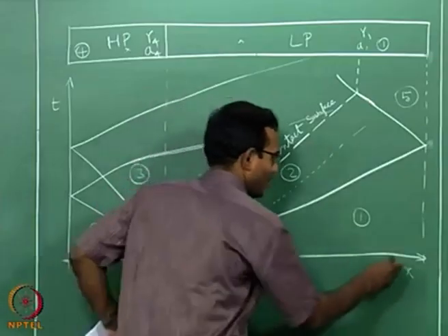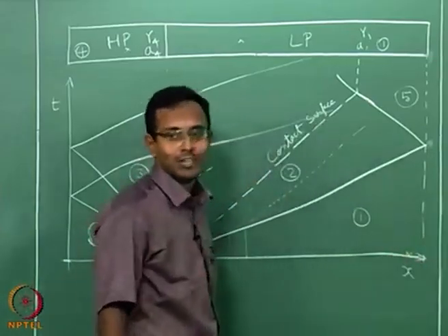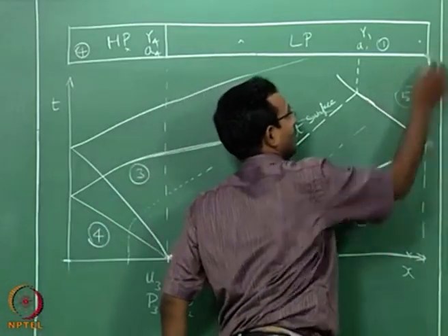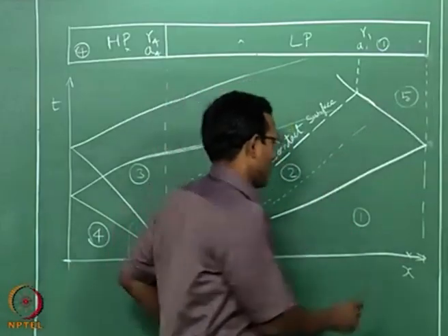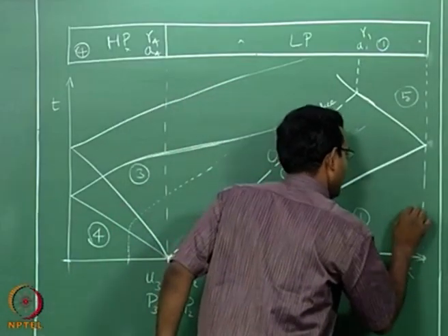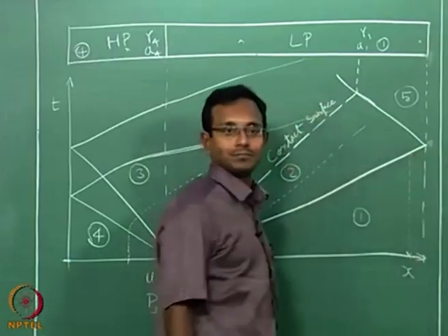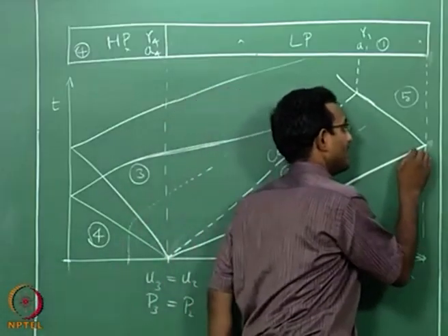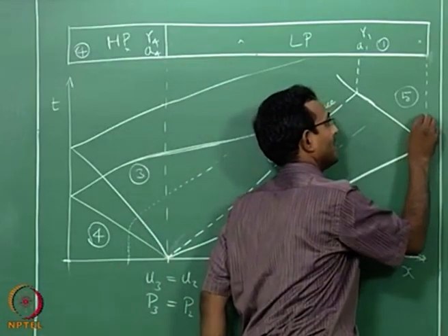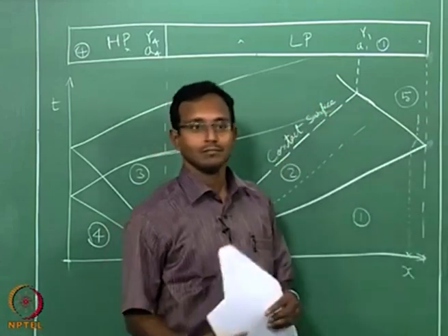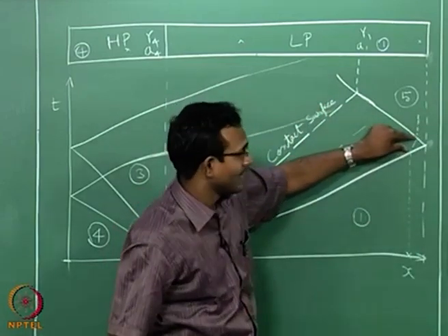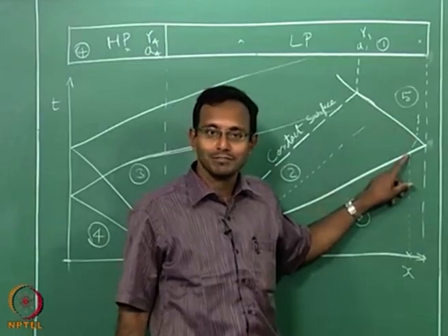If I think about this particular particle sitting here, this particular fluid element at this location, that fluid was sitting at P1 T1 for this long a time, and within a short time it got compressed and it is now sitting here. Okay. This is all the time it had. Shock is traveling supersonic, remember.